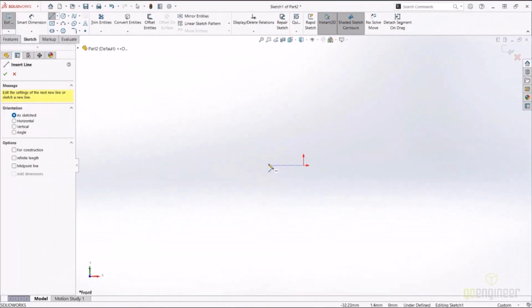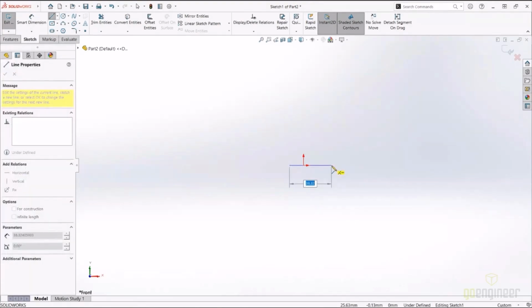So let's start sketching. And this time, I am going to pay a little bit more attention to the scale. I'm going to get a little, within reason, where I want the origin, because with the on-screen numeric input, I just click down one end of my line. And then I do watch for the horizontal automatic sketch relation. But instead of clicking the second end of my line, I go ahead and type the value. That's the on-screen numeric input. And then it's still chaining. So I just pull up. Now this one, again, this is just like the auto insert where you can only get the normal dimensions.